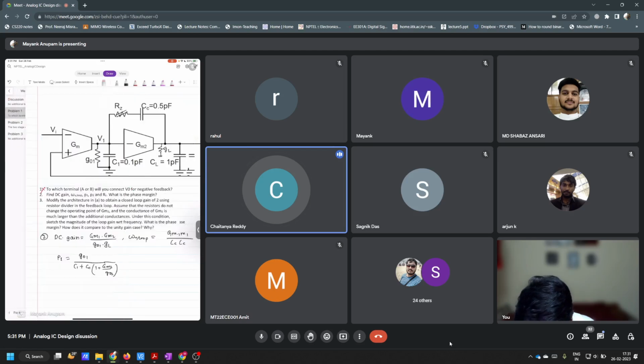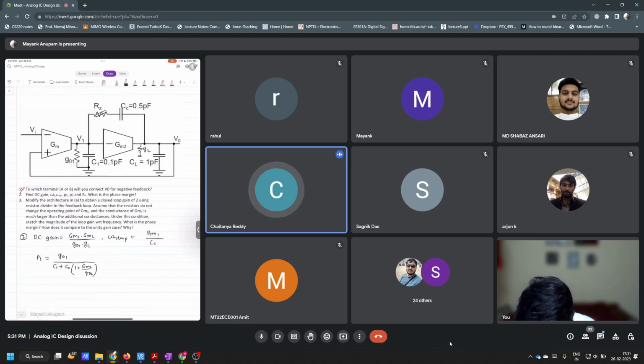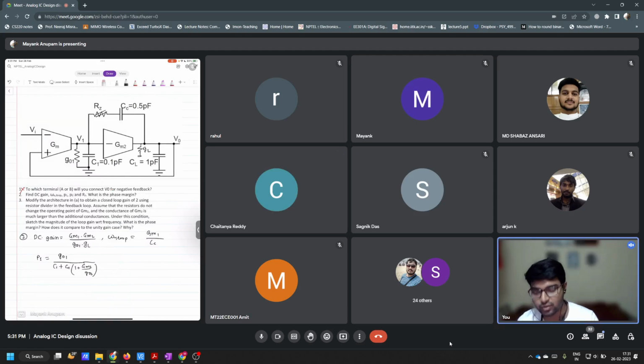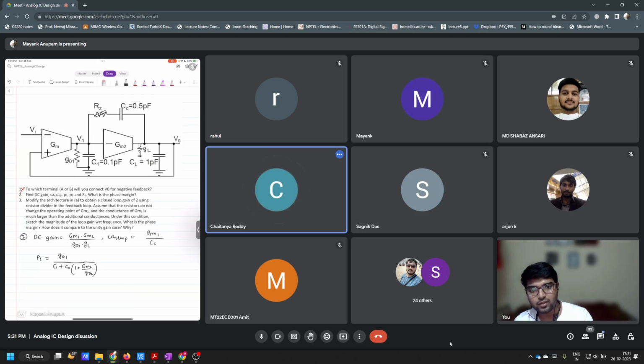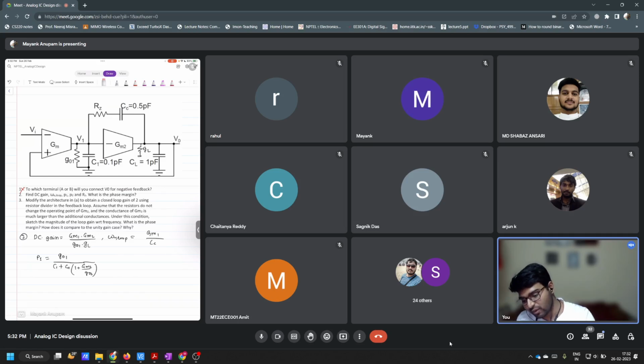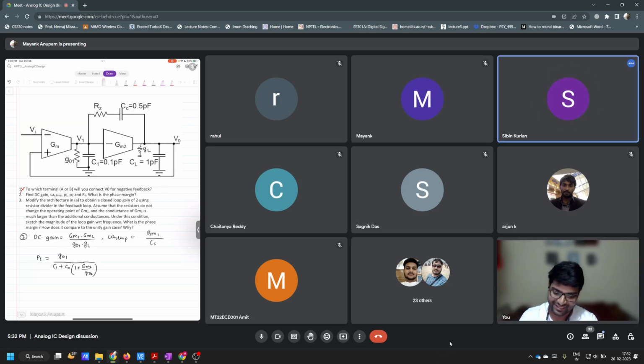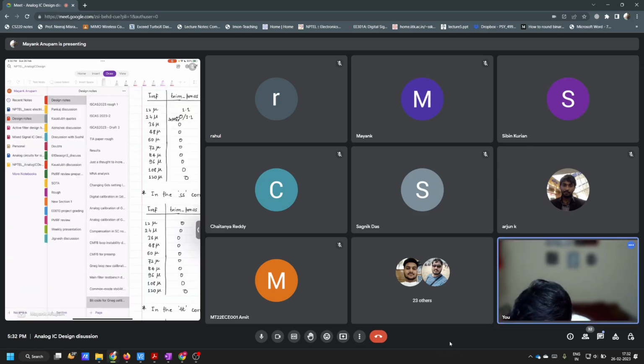After adding resistance, it is no longer going to be a second order system, right? Definitely, it is not a second order system. It is a third order system. But the third pole is going to be coming at very large frequencies, outside omega u loop. Have you done this calculation? It was told by Professor Nagendra to calculate. Did you write the whole loop and then calculate its P1, P2, P3? No. Okay, fine, so I did that.